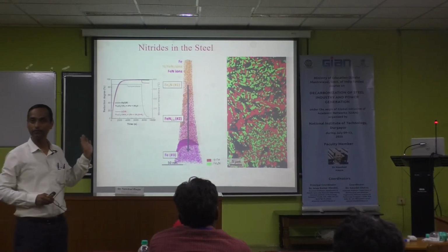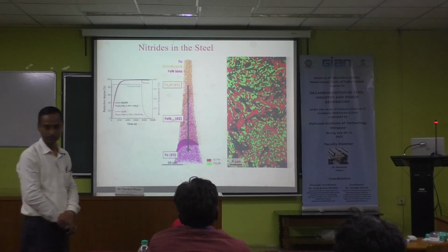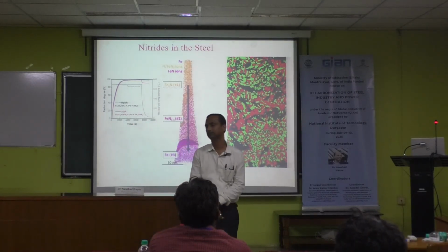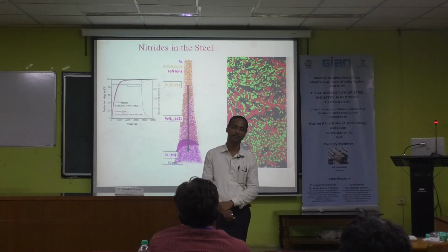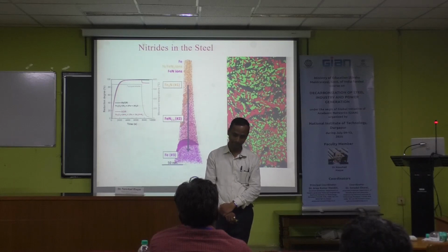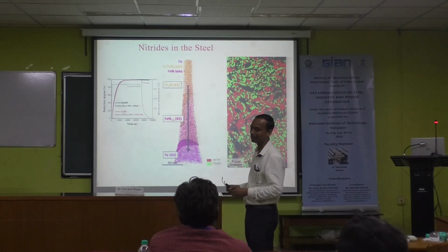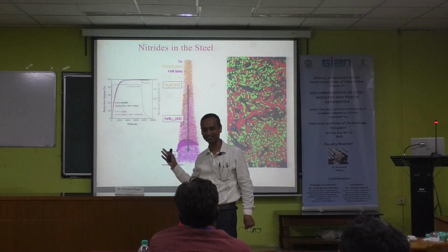Is there any problem if nitrogen absorption happens in the metal? It becomes very brittle. Or will this nitrogen give you some advantage or disadvantage? It is an austenite stabilizer, but at the same time you have a gas issue in the EAF. Sir, we are talking about the DRI only. We are not going into the steel itself.